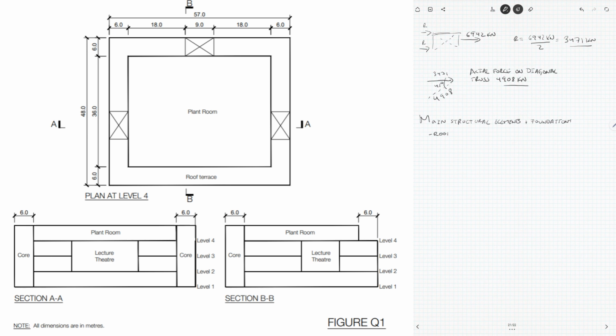Second main reason for failure is not doing the foundation design or foundation calculation. Third reason is not considering the serviceability, especially for large spans, cantilevers, other elements where deflection tend to be the most onerous case.